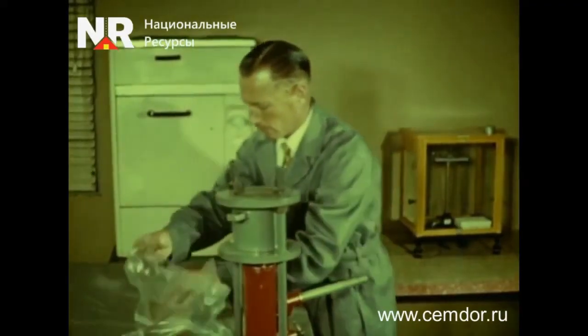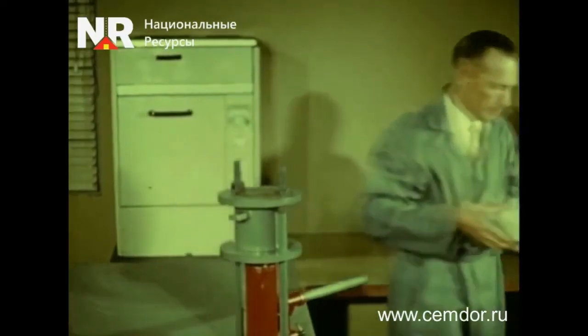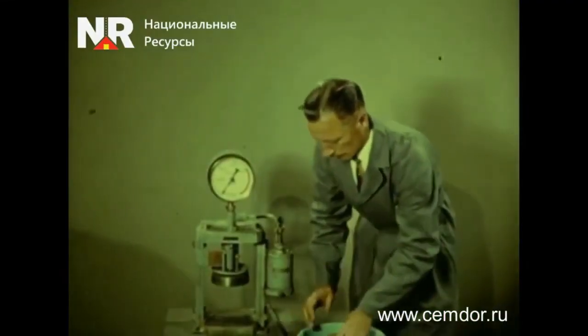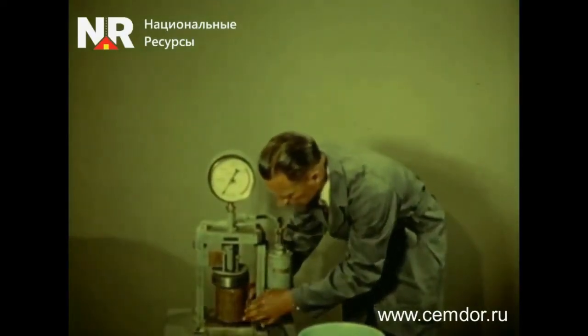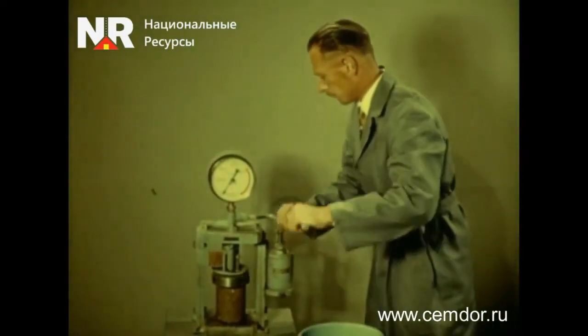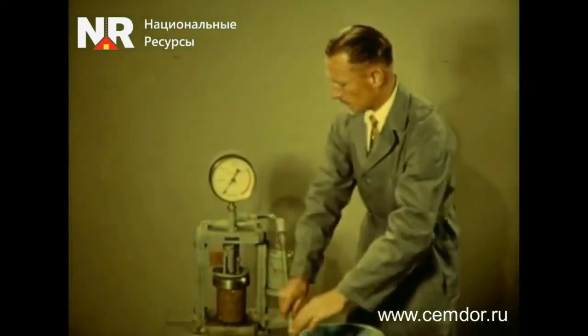Cylindrical samples are made from these mixtures by compaction. The compaction is carried out to achieve maximum density at the previously established optimal moisture content. The resulting samples are stored in airtight packaging for 7 days. After the specified curing period, the samples are removed and their compressive strength is determined using a hydraulic press. The results of these tests determine the required cement content to achieve the specified strength parameters.